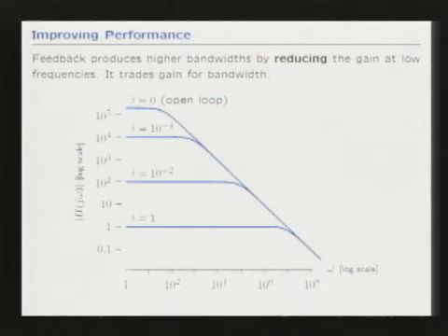If you think about what happens, the top curve here shows the response curve for a 741 op amp with no feedback. It has a pole at minus 40, to be a little more correct. So there's a single pole at minus 40. That corresponds to beta at 0. That's open loop, no feedback.